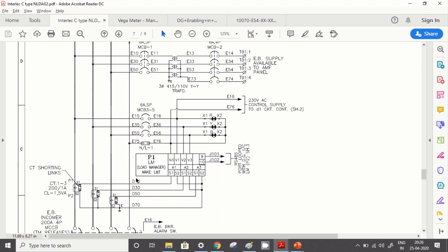But for any reason, if you are replacing the meter, at that time you have to remove S1 and S2 of phase R, S1 and S2 of phase Y, S1 and S2 of phase B, and properly insulate them, and after that immediately short this. Before removing the meter, first of all you have to short this, so that there is no chance of any potential developing, and after that you can smoothly remove S1, S2 and then put insulation tape on them. So that is how you always have to change the meter for any requirement.